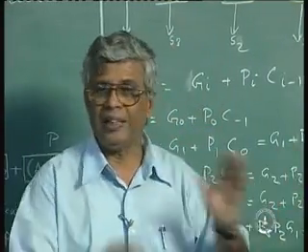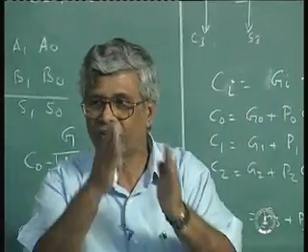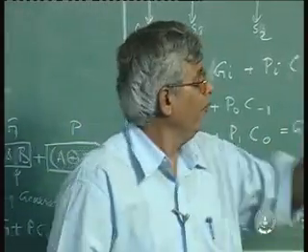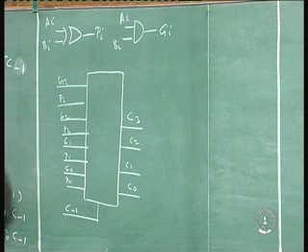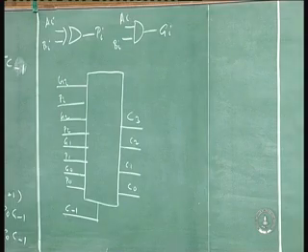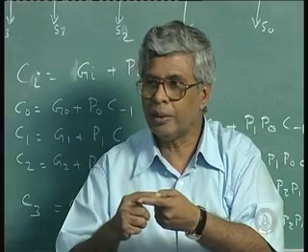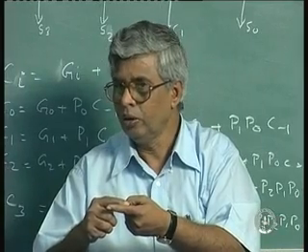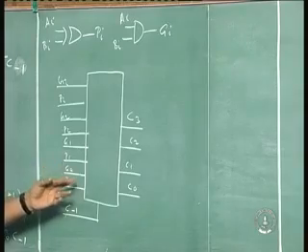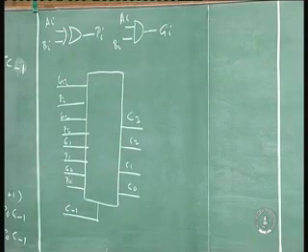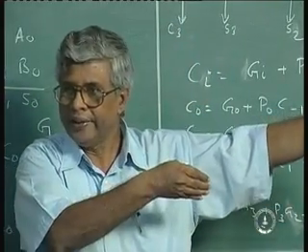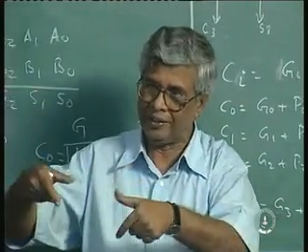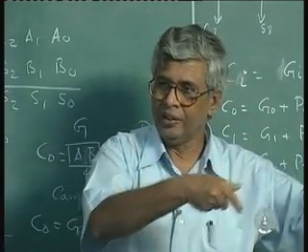So all these gates are only 2 levels, that is what I am trying to tell you here, the levels of transmission. The signal is given, A's and B's are given, one level to get Pi, and Pi and Gi are calculated simultaneously. So after one level of computation or switching, Pi gets computed, Gi gets computed. So that is fed here. After 2 more levels I get C's. So 1 plus 2, 3 levels, whereas if I have a multi-bit thing, it is going to take several, where each one of those is 2 levels, so there is a multiplication effect, it goes all the way.